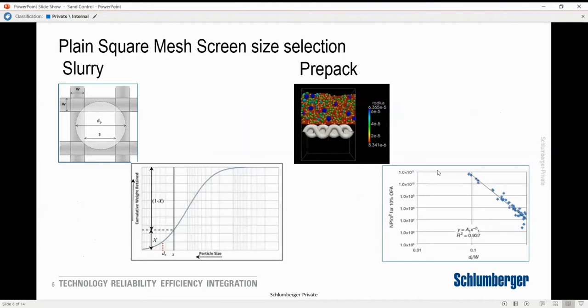So what's the new model of simulating and finding the screen sizes? Because doing the PST tests is quite complicated. They are costly. So at least before doing the test, you need to have some understanding of the right size to test, because without knowing the certain directions, you may end up with 10 or 15 tests which are consuming your budget.